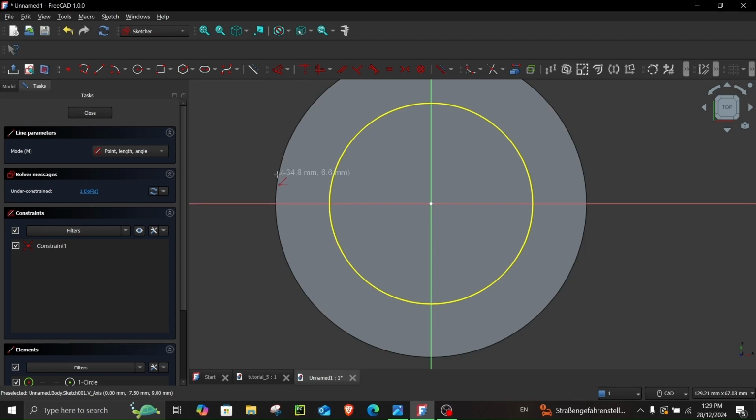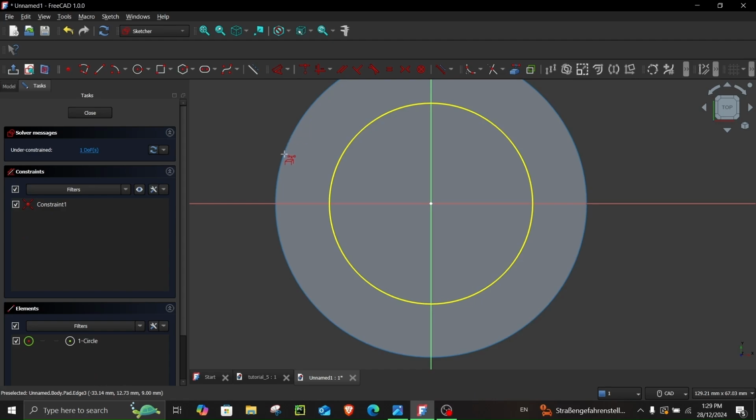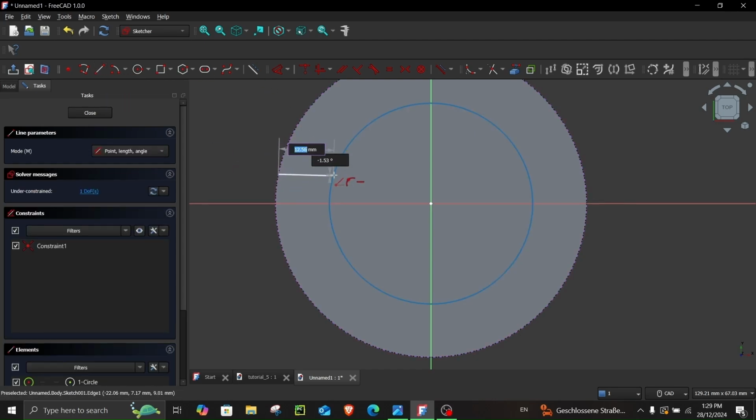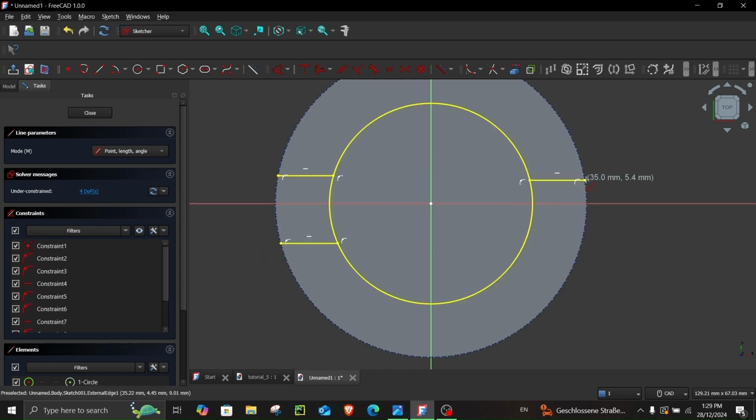and now you can see you cannot snap this line over here with this circle. So in order to do that, choose this option, create external geometry, and then you can see this has highlighted this blue circle when you hover your mouse, and once you click it, you will see this pink dotted line over here. Now you can press escape to exit from the tool, and then let's click here, create line, click here and then here, and similarly for this side as well.